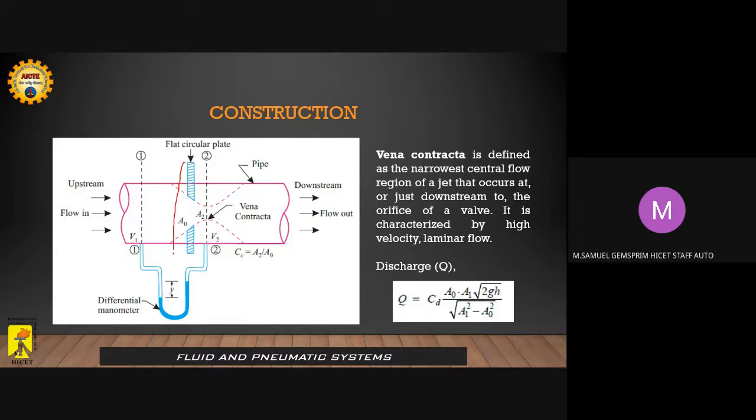This blue color one is the orifice, which is of a crosswise inlet, so thereby it simulates the condition of a venturi meter. It is not exactly the condition of venturi meter, but it simulates. So the fluid comes in and it is getting deflected, and it is almost following the same kind of fluid flow as in case of our venturi meter. The velocity increases, settles down, again the velocity is getting back to original condition.